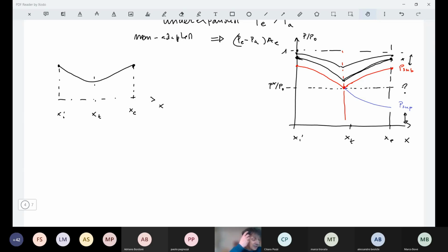So entropy increase is related to total pressure decrease, and when we obtained the area ratio from the Saint-Venant equation, we simplified the total pressure.